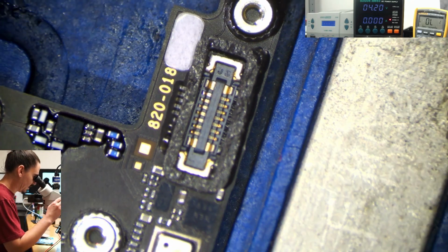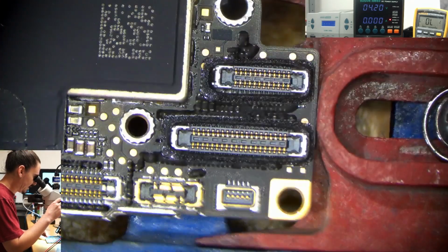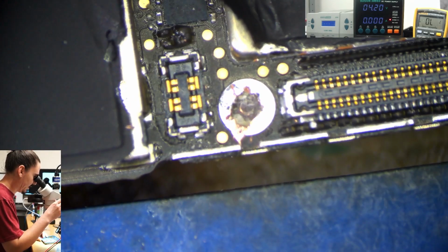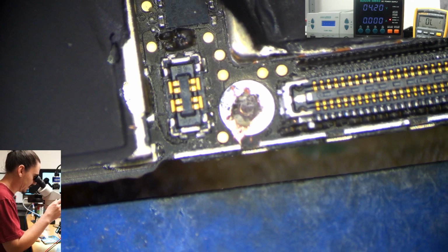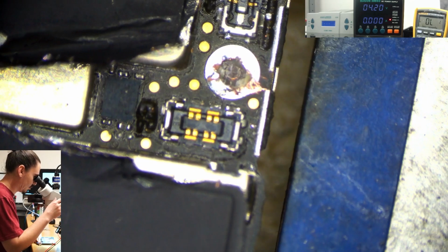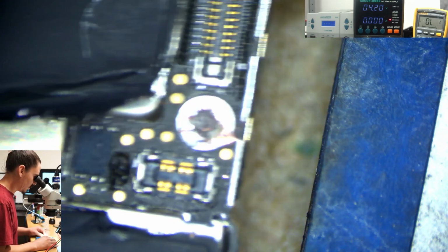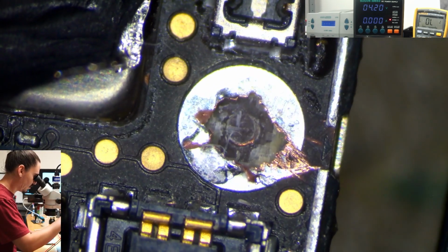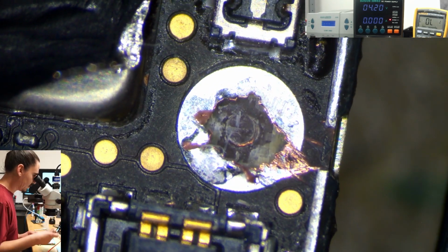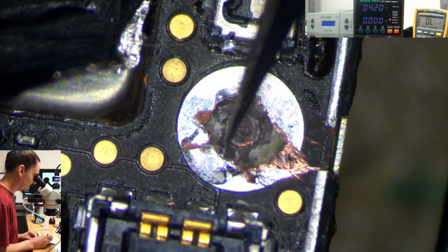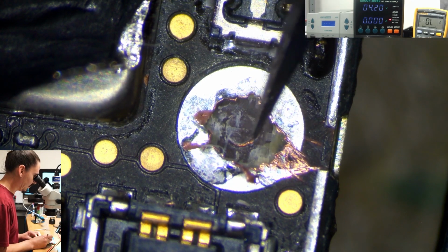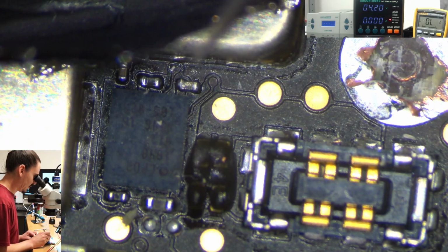So I'll take my parts now, I'll plug them in, and let's see if we have image. There's a possibility I still don't have image on this device because I have a lot of image lines going under that screw hole as well. It's also interesting, I'm not sure what line it was touching. There's not too much copper exposed, so I guess just something right there is part of that 1V8 line.